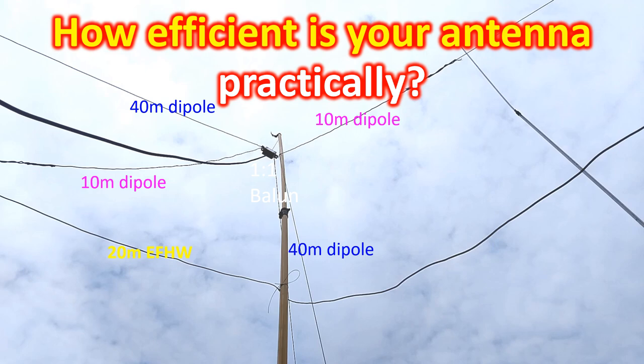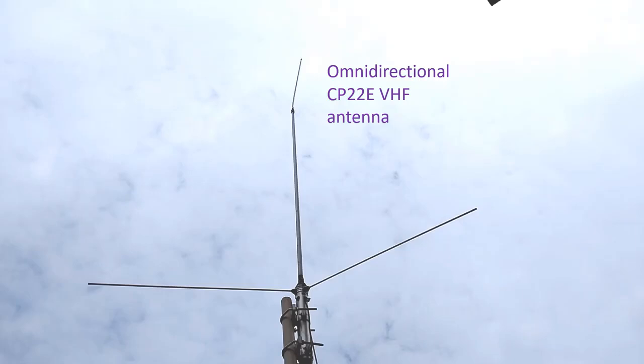Gain of the antenna will be equal to the product of efficiency and directivity of the antenna. Directivity of the antenna is usually mentioned in terms of its front to back ratio. In other words, how efficient the antenna is in directing the signals in one direction while cutting off radiation in other directions. High directivity will usually be associated with high gain and low beam width.